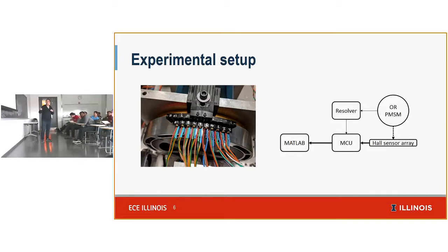And this is also mechanically coupled to a resolver. Both the resolver and the Hall sensor arrays are sampled at the same time regularly with a microcontroller, and the data is passed into MATLAB for training of the neural network.